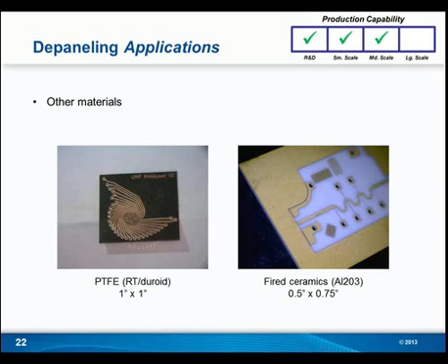We can process ceramic 15 mils thick pretty efficiently with a 6-watt source. It all depends what your current method is and what your goal cycle time is. We have the stronger UV laser that can cut it faster. So as I said, we would have to talk a little more about your goal cycle time. But also keep in mind we have an IR laser that we can use for cutting ceramics. The trouble with ceramics is you can get micro cracks after the fact if you use way too much power. So it really depends on your application and your goal cycle time, but we have options.